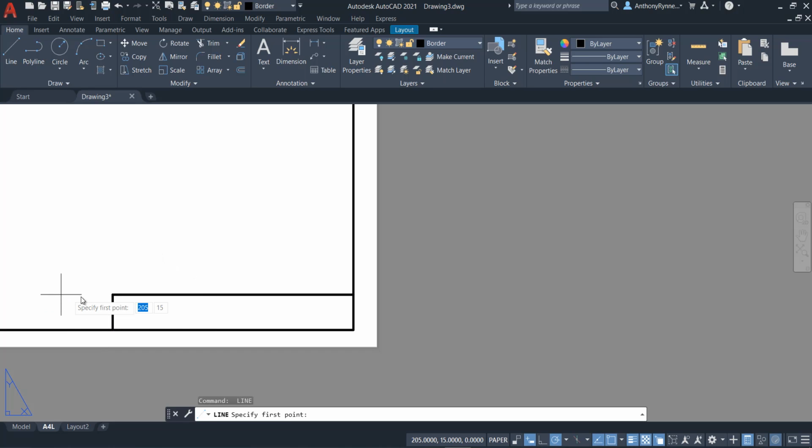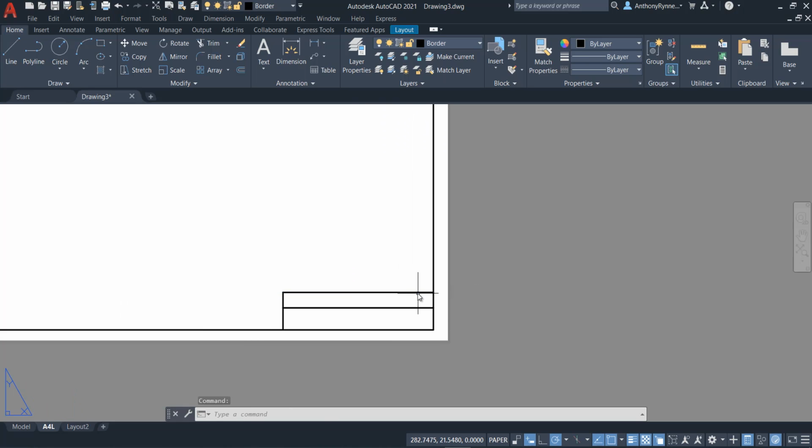Press the space bar again and you can start from here. Now I'm going to track up. This time I just want to go up 7 millimeters. So just type in 7, and as you go across here now, if you've got snap on, that's going to cause us a problem. My recording system is set up to use F9. If I want to turn my snap off here, I'll have to, in the middle of this command, by using an apostrophe. You won't have to do this, you can just press F9 on your system. I'm just going to turn my snap off, so I have to do it this way. So to show you, click there, and with my snap off, I can draw my line across there and intersect with the intersection there of the border.